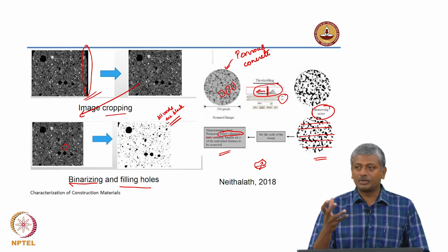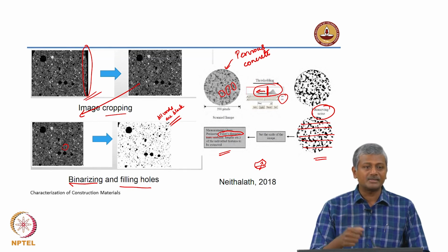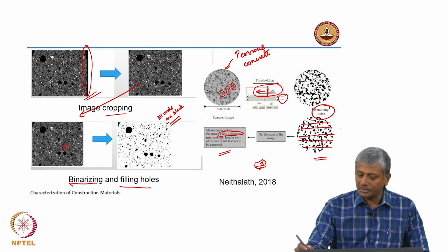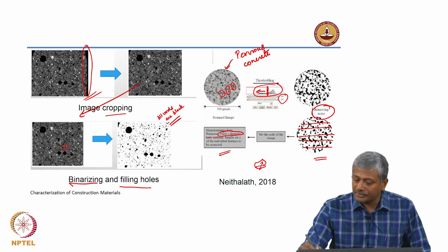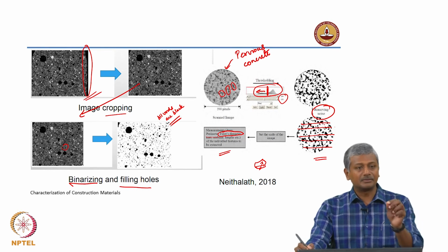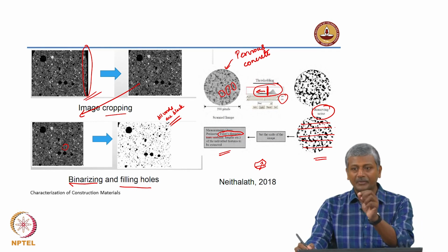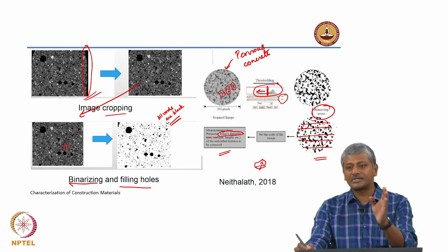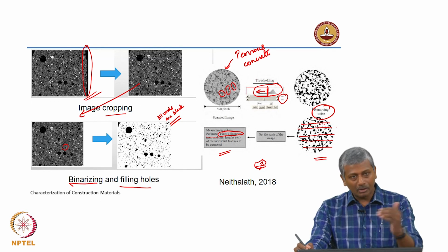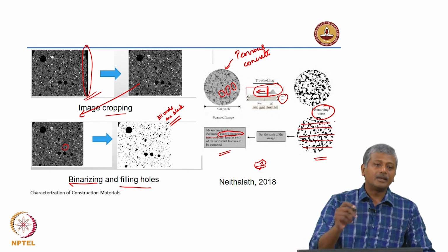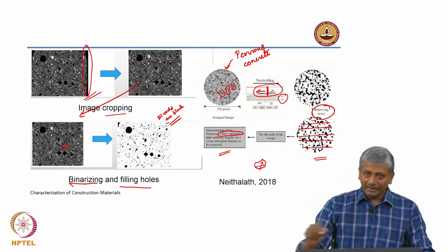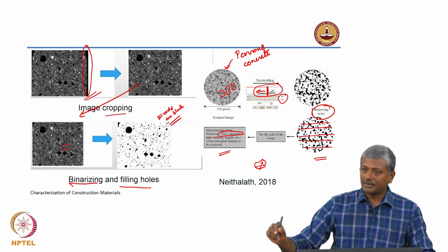You need to understand this to actually relate this to the volumetric proportions. So, what I am doing is I am just taking a line across the image, and whenever my line crosses a black, I am marking this as 1, 2, 3, 4, 5 like that. Each pixel is actually monitored across that line, and the number of pixels that are black versus the number of pixels that are white on a particular line gives me the number of black pixels per unit length.